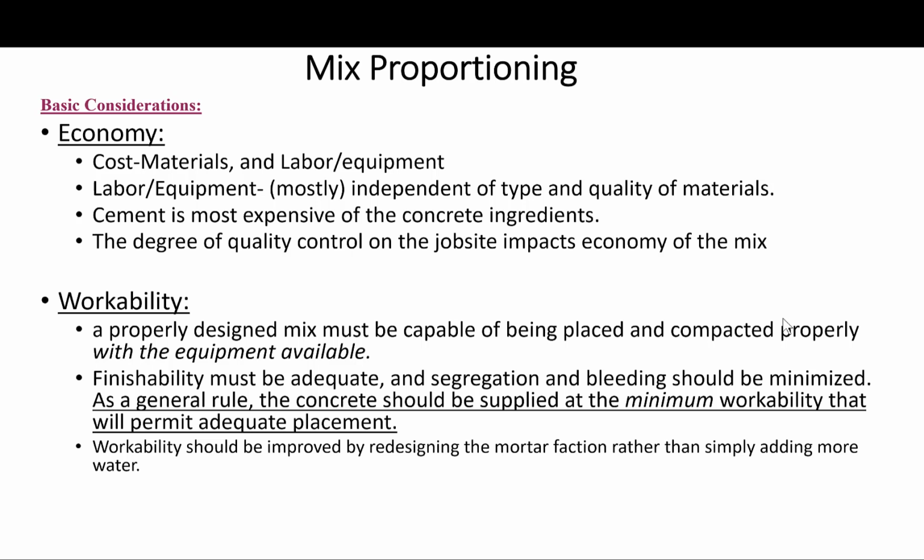On small jobs, for example, it may be cheaper to over-design the concrete than to implement a quality control program in conjunction with a more cost-effective concrete. So again, implementing a rigorous, watertight quality control program in the field may not be cheap. If it is not worth the effort on small jobs, over-designing is much cheaper. I hope you get that.